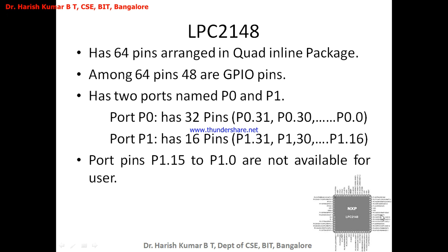That means you can find pins on all the sides. Since you find pins along all the sides, it's called a quad inline package. If the pins are at only two sides, then it is called a dual inline package. Since here the pins are found on all the sides of the IC, it's called a quad inline package.